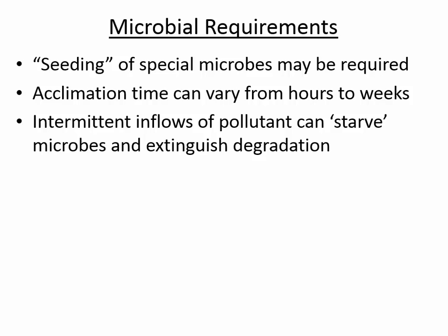In order to treat some of these trace organics, it's specialized bacteria that can break them down. They're kind of rare, exotic species, and so if you do have a treatment plant that is going to be receiving an industrial wastewater that has one of these trace organics, usually to get good removal, you have to sort of colonize and populate an aeration basin with the species that are required.